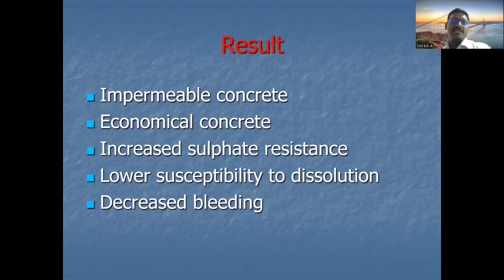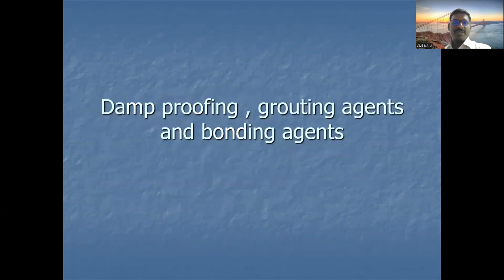Then lower susceptibility to dissolution and decreased bleeding. So bleeding of concrete is also decreased by adding this pozzolanic material. So these are all the major results we will get from the pozzolanic material if we add it to the concrete.